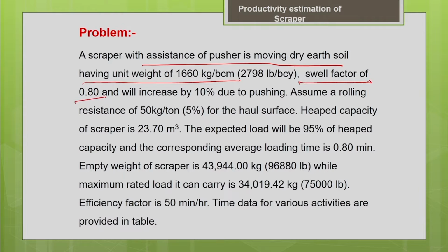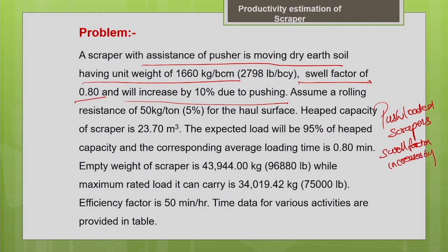With the help of the swell factor, you can do the conversions, like from loose volume you can convert it into bank volume or vice versa. And you should know that the swell factor will increase by 10% due to pushing, particularly for push loaded scrapers.